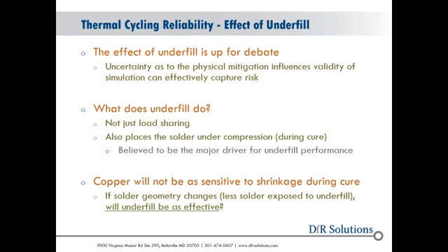So it's not the load sharing, it's the fact that the underfill is placing the solder under compression during the cure process, pulling the die down, shrinking around the balls, and it's the compression which is believed to be a major driver for underfill performance. We'll talk a little bit about an aspect of that which we call mean stress. But we believe here at DFR that the copper pillars are probably not going to be as sensitive to that benefit. I have less solder exposed to underfill. It's not compressing the entire flip chip bump.